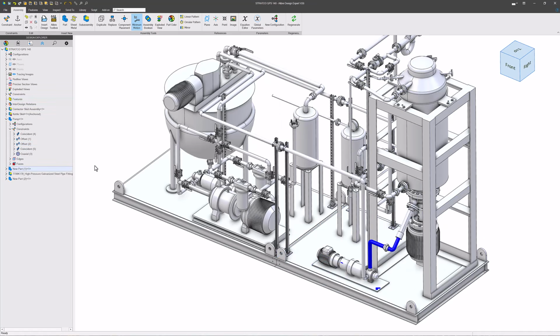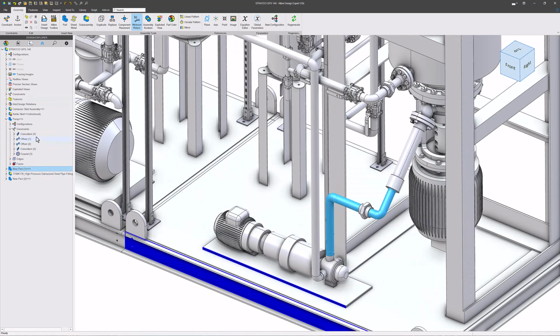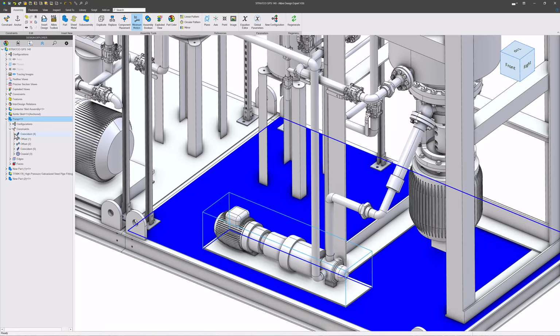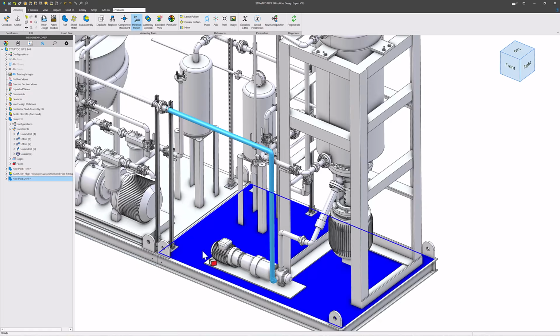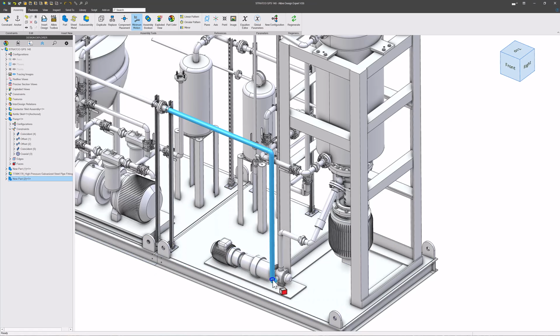They are each their own unique files. They're not part of the pump. And so we have an assembly that will update itself according to how parts locate. And this is why we edit in context. We created these pipes in the context of the assembly, so as the context of the assembly changes, the pipes update automatically. And so the big question is, where do we draw the line between when do we want to edit in context versus when do we use traditional constraint and dimensioning techniques in our assemblies?